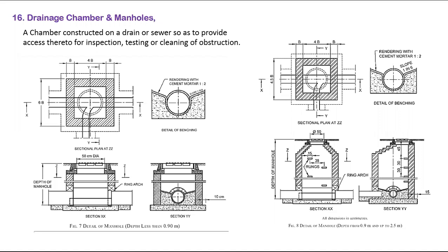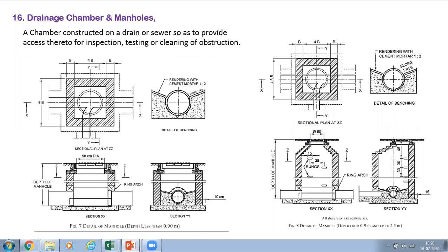You should not provide the wall thickness. Inner size means length, breadth and height or depth, you have to provide. That's all. From our plumbing engineering point of view, we have to give length, breadth and depth, and the pipe inlet level. The other outer size they have to decide based on the civil design. The civil designer will do the whole construction design. With our level and the pipe size, they have to install the pipe and everything.